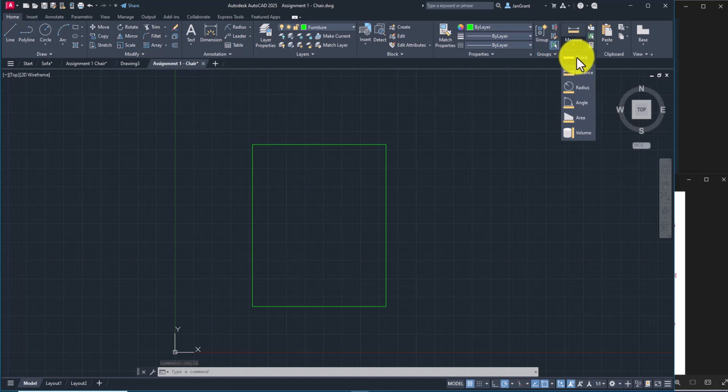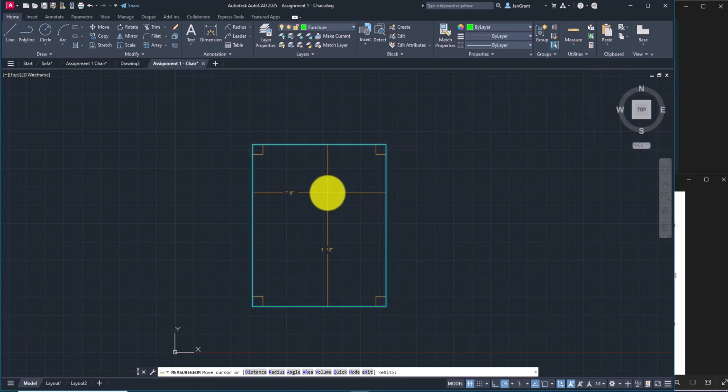And you see the difference? The difference is that it's showing you 1 foot 6 inches instead of the 18 inches. You just changed the way that it looks at those numbers. And later in the next assignment, we'll take a look at how to enter feet and inches. This one's basically inches. I'm going to use the escape key to get rid of that. And now let's go back and take a look at what else I need. So we just drew those lines.